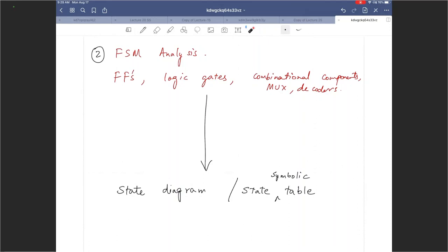The only difficulty in this is you will have to be really careful tracking your Boolean algebra, because you're using Boolean algebra to relate all the inputs and outputs, whether the inputs are going into the flip-flops. At each point in your circuit there is a logic expression, so you will have to be careful with the Boolean algebra that you use to do this.